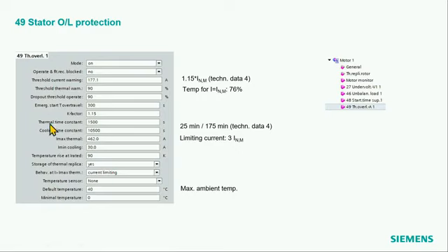Therefore, this might tend to overshoot, so I take a limit current for this model for the temperature calculation which is around the starting current of the motor, which I think is a good approximation. Then we use, not the starting current, but a threshold which is under the starting current. So we have a kind of balancing out of the temperature rise, because I want somehow to get the temperature part of this starting current, but I don't want to have too much. So it's a kind of compromise here.